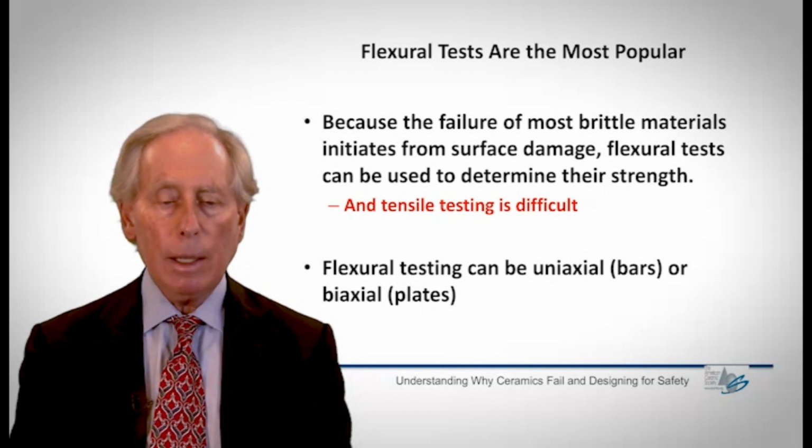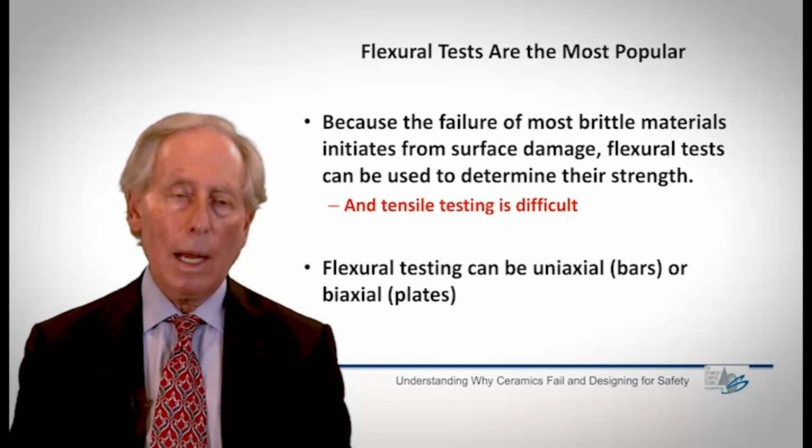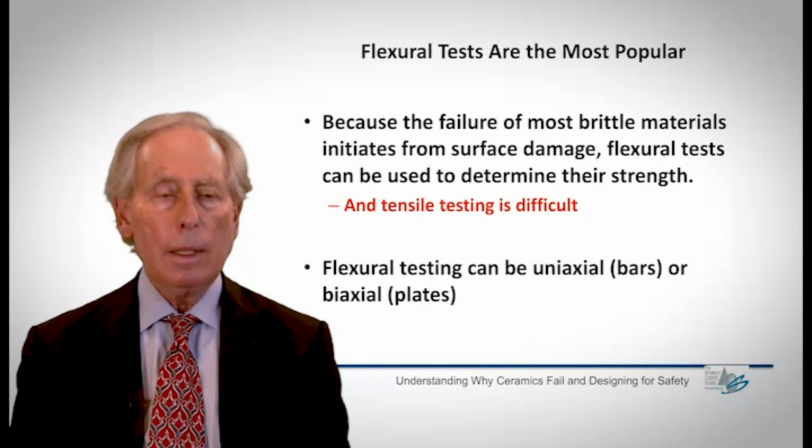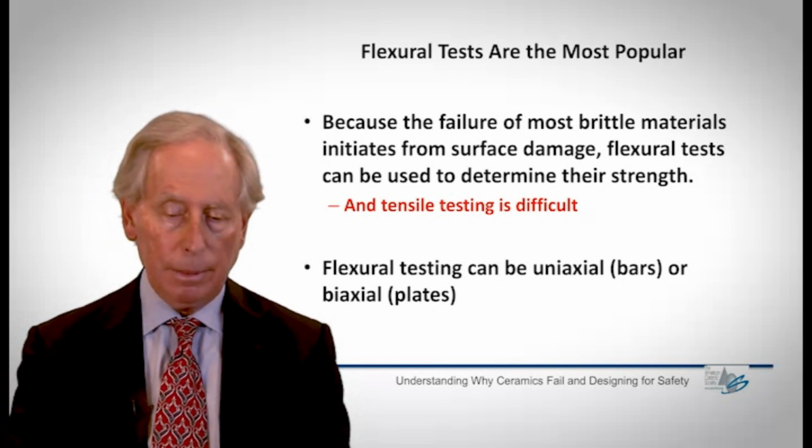In other words, machining and polishing of flexural test specimens must mimic that of machining and polishing of components. Otherwise, my extrapolation from testing of specimens to testing of components simply will be incorrect.